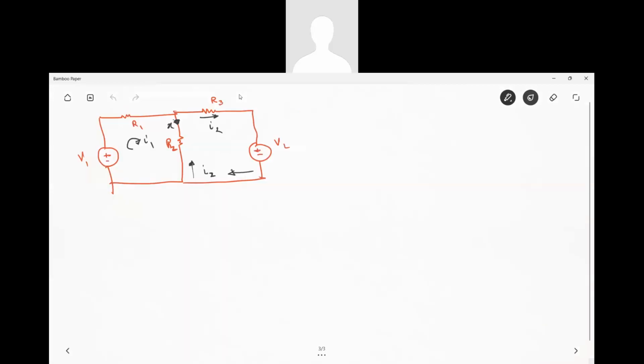So the x direction is now reversed in this scenario. X is going like this, so I1 will not change. I1 is incoming, X is also incoming, and this is outgoing. So if you apply KCL again there, you see that I1 plus X is equal to I2. So the X value changes: it is I2 minus I1, correct?